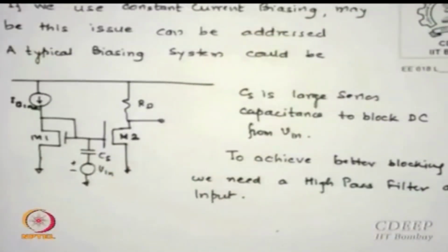So if I use this circuit and modify it slightly, what he said, and I agreed with him, is that yes, I can use current biasing independent of my actual transistor. I put my bias circuit on the left side. That is what every analog designer will find, there will be a biasing block. Of course, we will learn separately how to create references, both current references as well as voltage references, which will make this constant. So that is another part which we will learn. With that, this whole circuit will be called the biasing circuit.